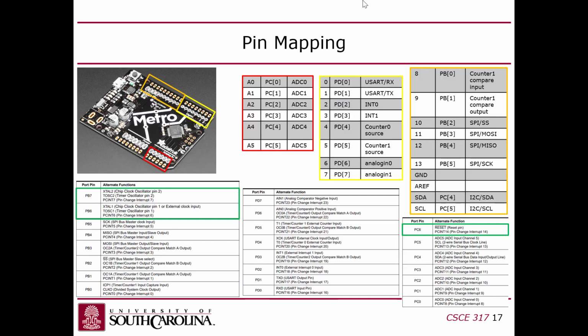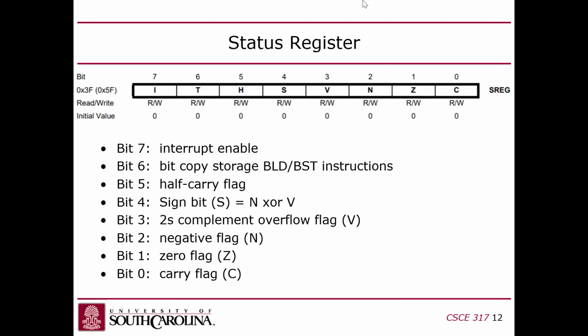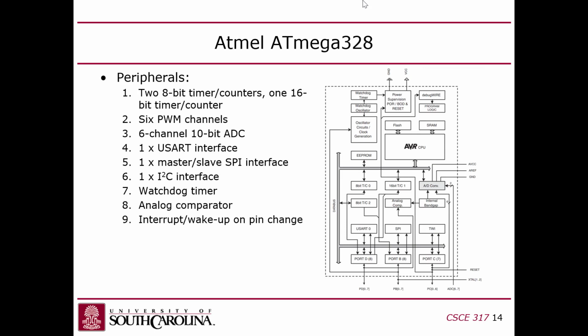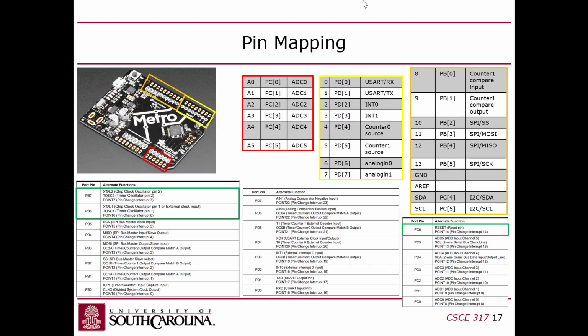And you actually saw this even in the status register, right? The status register has 7 bits that are set from the ALU, not an I/O device, but the ALU. But then there's a bit that the user is supposed to be setting. So you have kind of a mixture of inputs and outputs even in one register. And some of the I/O addresses are like that as well.